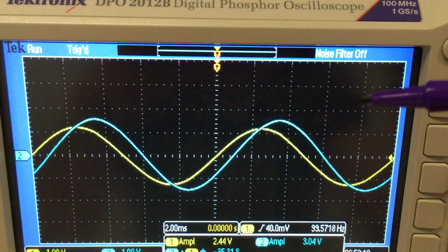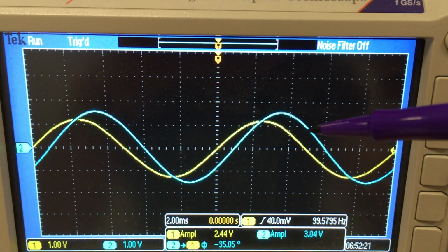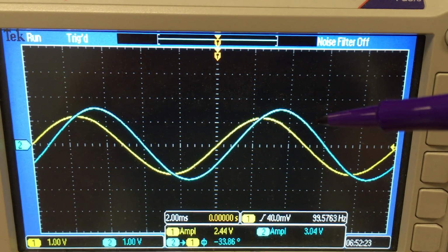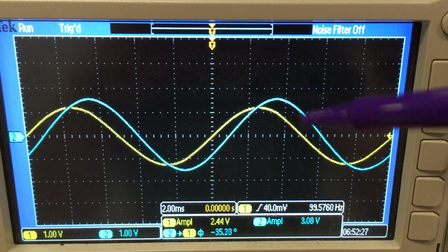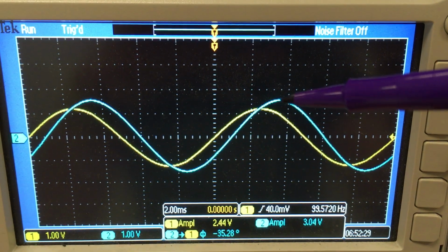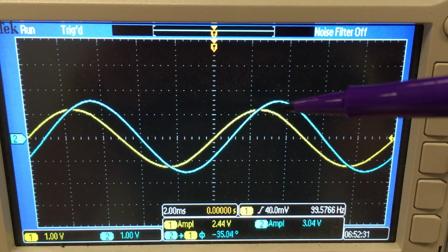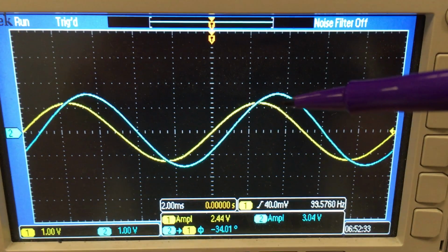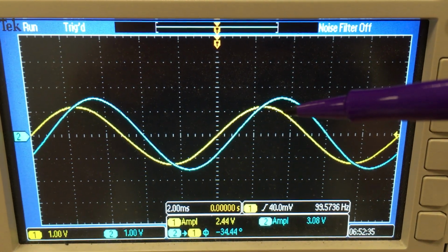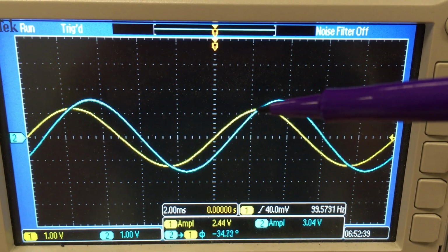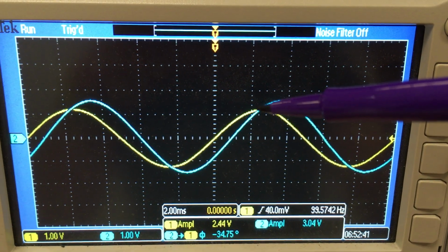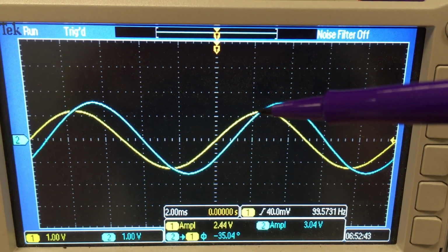So eventually the power source just won't have enough energy to push any more charges on there, and the capacitor would be fully charged, quote unquote. That never really happens in an AC circuit. These oscillations are happening so rapidly that the capacitor never fully charges up or fully discharges. But that little bit of reluctance to add charges is the source of this apparent resistance. It's called reactance, and we'll look at it in just a few minutes.